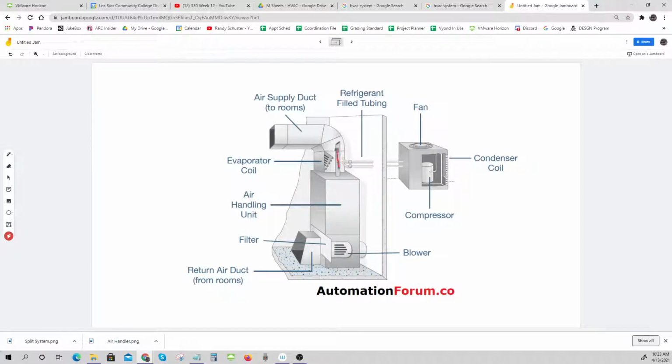And this tube right here is kind of interesting. That's your makeup air or your exhaust air, because you always want to get rid of some portion of the air that returns. Let's say I've got 100 CFM coming in. You might want 10 CFM to blow out the roof so that you can get new air through here. So that's just a thing. But this one has an air handler. They've even said, yeah, you need a filter. Yes, you do. We didn't talk about that on the last one. We're not going to talk about it now.